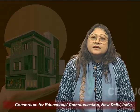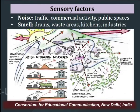The next important factor is the sensory factor. Senses mean what you feel, what you touch, what you hear, what you see. So, for site conditions, the sensory factors are majorly noise and smell. Noise is generated from traffic, commercial activities, and public spaces, and smell comes from drains, waste areas, kitchens and industry. While doing site analysis, these two factors come under the sensory factors because they are not present or documented anywhere. They have to be evaluated by the architect and the designer when he goes on the site.